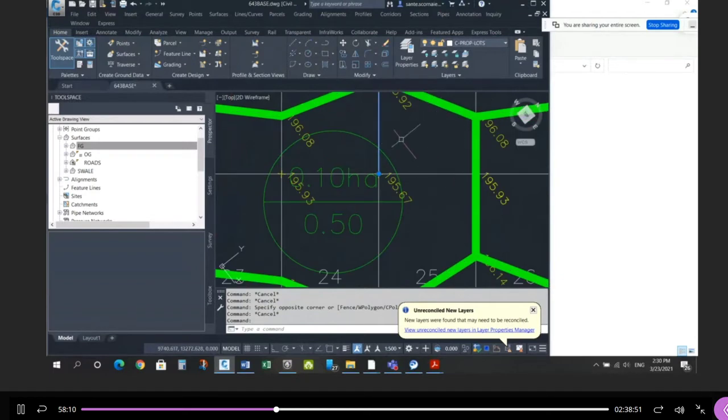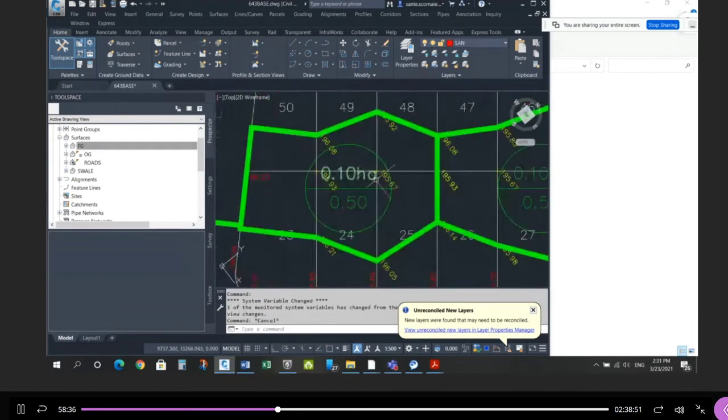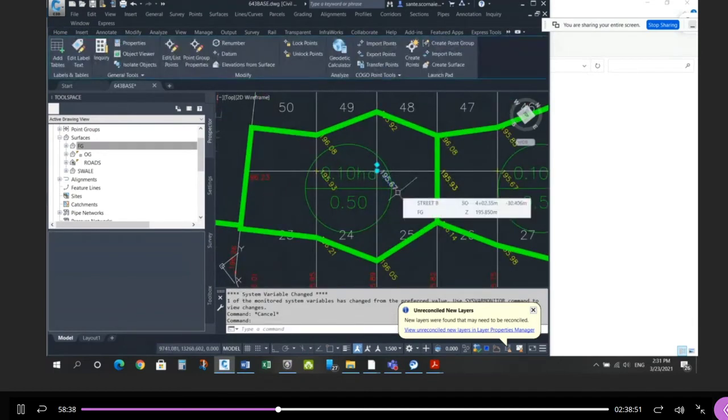This area, there's only one backyard tributary to this. If I put the catch basin here, I have to take flow across this property line and across this property line and then put it in here. If I come the other way, I'll cross this property line once and I'll get into this catch basin just the same. So I don't want to have all this accumulated flow crossing one more time. I don't want to cross this one more time, so I'm going to put it here. So basically, when you look at it, if this is your low point, put the catch basin on the longer swale, swale catch basin side. So all this flow, pick it up before it crosses one last time.